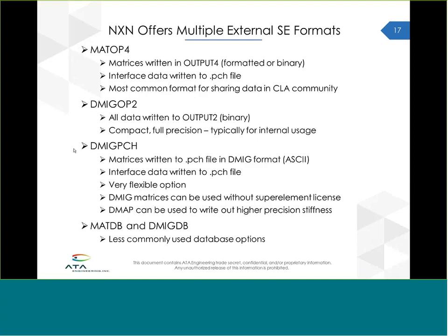There is some loss of functionality. So, for example, if you do this without the superelement license method, you can't do data recoveries from inside. So there are trade-offs, of course, but that's a pretty convenient way to attach a matrix to some other structure, if you don't or can't use superelements to do that. And then the last two, the MAT-DB and DMIG-DB, everything is written to the master and dball binary files, which can be very, very large files. So those aren't used very much, but they are there.